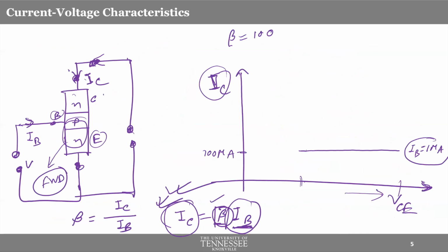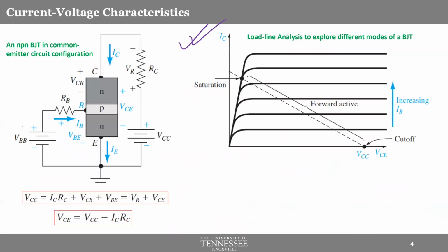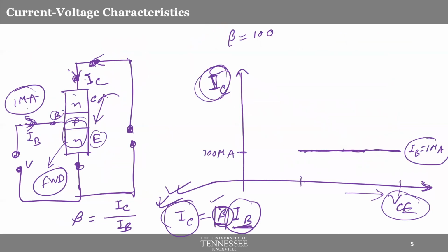So you are dealing with a reverse bias scenario here in this junction with respect to VCE. That's why this will ideally remain fixed. And the level of IC that you'll see will be directly related to how much IB you provide. If you provide 1 microampere IB somehow, by the way, I'm talking about providing a current, and that's exactly the same as providing a voltage and adding a resistance, right? This resistance and voltage source will eventually create a current. And that's why I decided to simplify it with IB.